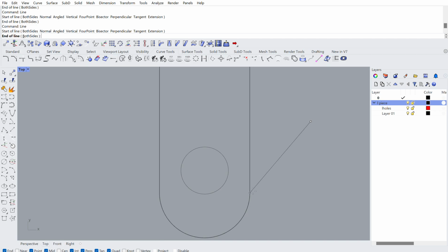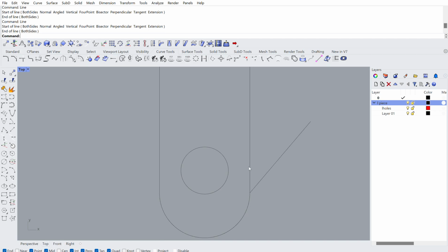It'll find, say, the end of this line, so I can use that as a way to snap between sections. I use that a lot when I'm setting up construction geometry, because you can't do things like you do in SolidWorks or Fusion 360 where you add your dimensions or constraints after the fact. Rhino is direct modeling, so where you put it is where you put it.